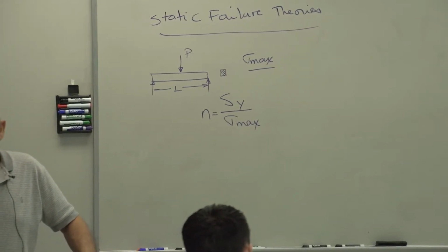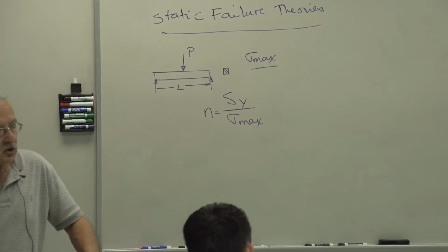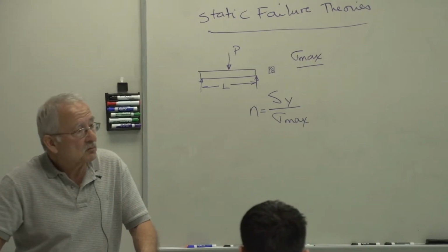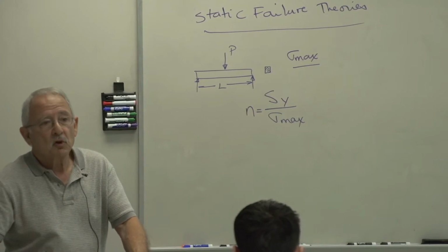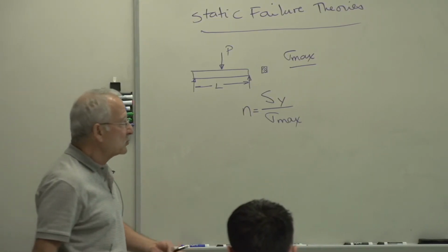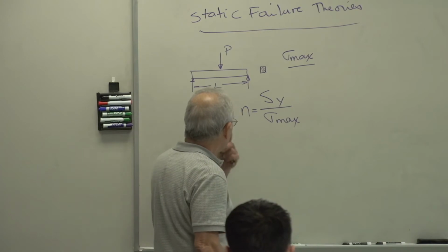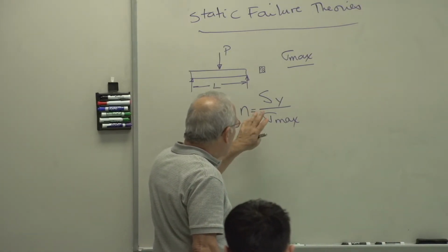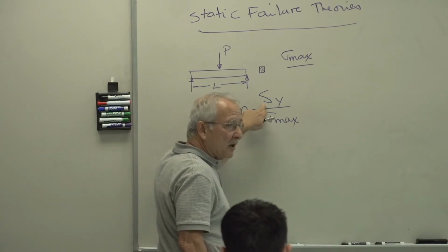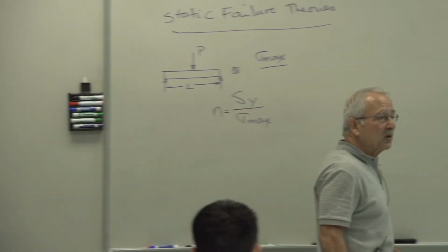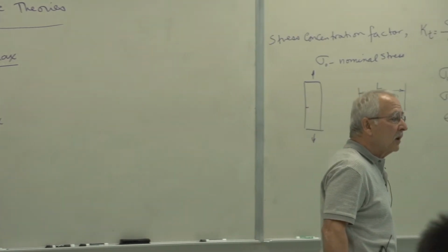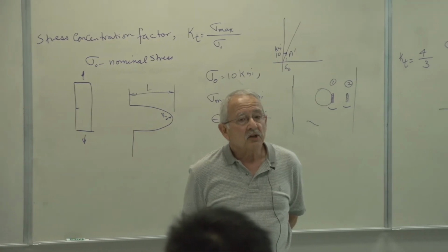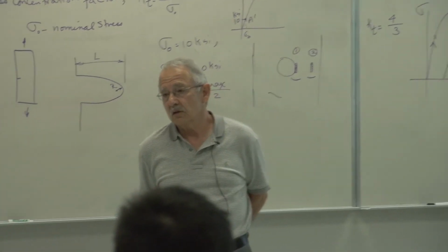Factor of safety is basically the ratio by which you can increase the applied maximum stress before you reach a threshold stress. Threshold stress may be yielding, may be rupture, or whatever else you may want to define. In this course, S represents strength, and sigma represents stress.